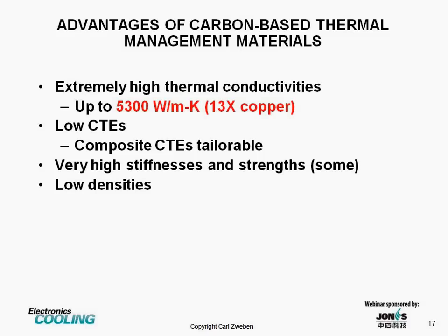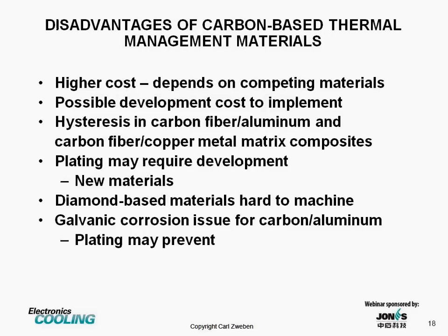So what are the advantages of carbon-based thermal management materials? Extremely high thermal conductivities, up to 5,300 watts per meter Kelvin, which is over 13 times that of copper. They also have low coefficients of thermal expansion, and if we're looking at carbon-based composites, they often have tailorable coefficients of thermal expansion. Some have very high stiffnesses and strength, and almost all have low densities, certainly compared to copper.